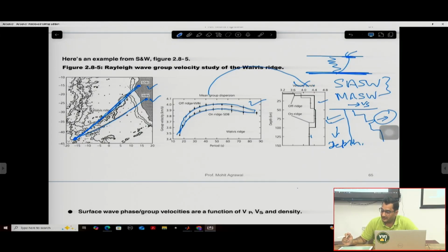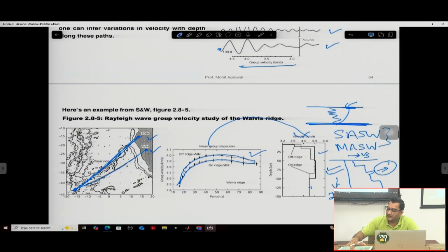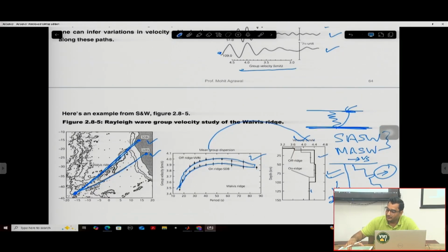So for safer construction designs, you will have to go through those micro-zonation steps one by one. First you need to make your maps for the PGA or the spectral acceleration at the bedrock level, and thereafter you may do the site characterization, and then you come to the surface using the site response study to find out your PGA values at the surface. And if further analysis is required for landslide and liquefaction, then also you may do so.